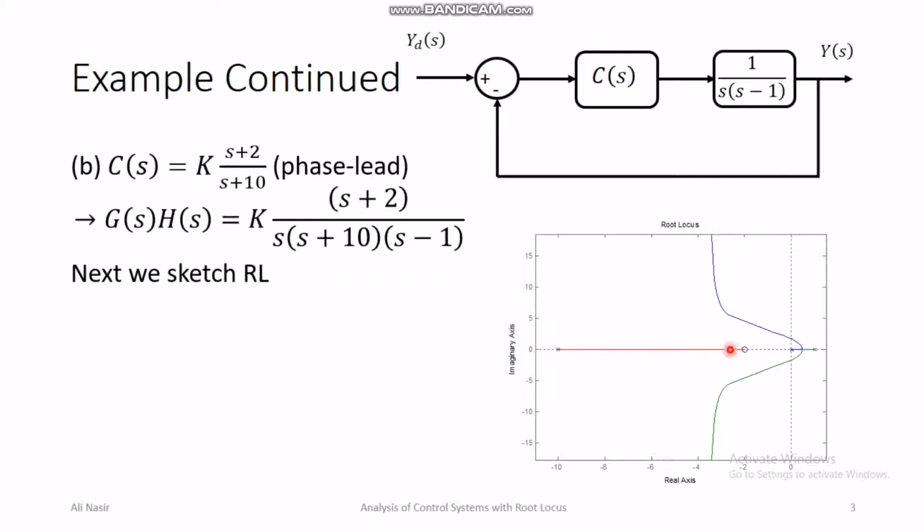is increased. So you can see that with the phase lead control, unlike the proportional controller, we are able to asymptotically stabilize this feedback system with large enough gain. When you have zero gain, the poles will be in the right half plane. You increase the gain, this pole reaches here, further increase the gain, and there will be a point where there will be a j omega axis crossing.